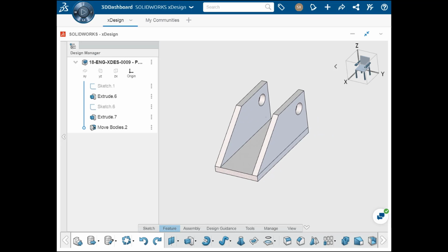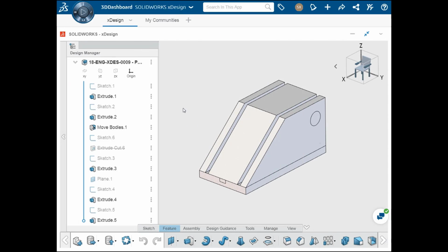At this point, I want to utilize another multi-body command, the Combine feature. To show you how this works, I'll skip ahead to include another body in this design. Now you can see that the gap is filled by another body that can rotate around the pins in the back. But take a look at the front. There's a notch overlapping with the base. This is a piece that is attached to the body in the middle, but it hasn't been cut out from the base. They're overlapping. To remove this section out of the base, I can use the Combine command to create the cutout of the exact same size.